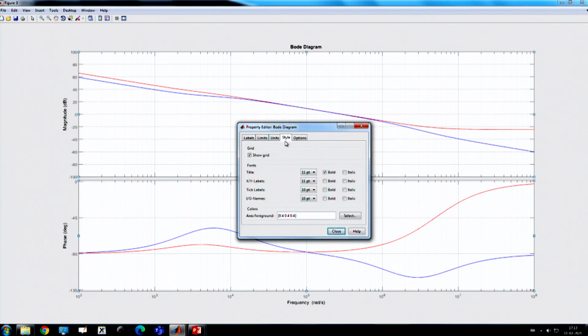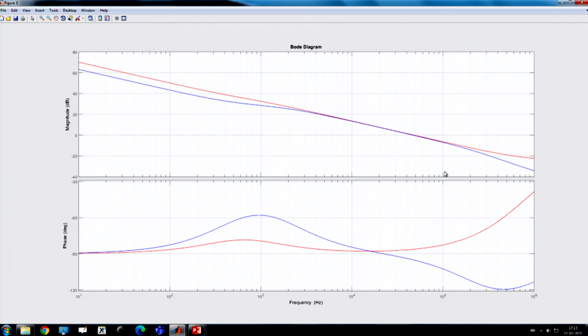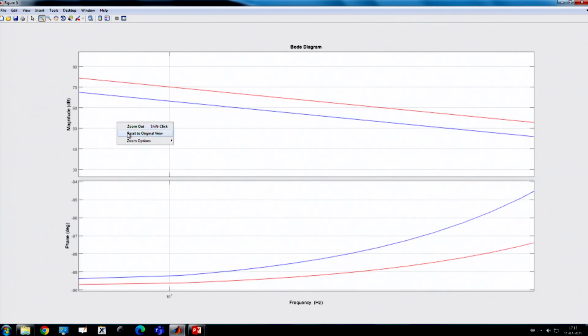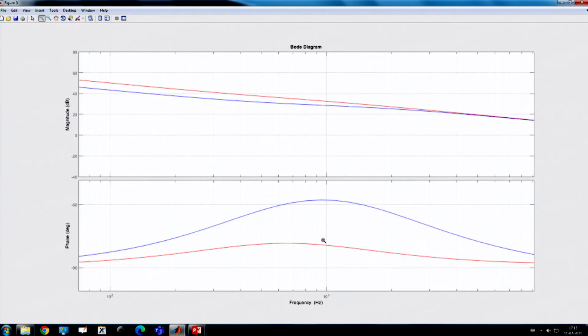Okay. So, if I take the limit, because this is our switching frequency. Because the current loop gain is now starting to fall, they are not exactly identical. Particularly you will see the improved model provides more phase, roughly 20 to 30 degrees, around 20 degrees of phase boost using the improved model.